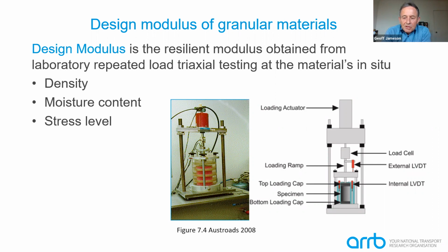I think in terms of the deformation characteristics, we don't have so much concern about the modulus characterization with this test. The concern relates to its use for permanent deformation, because we're applying an axial load, a vertical load. We're not applying a rotating shear stress in this test, and that's our concern about the use of this test.